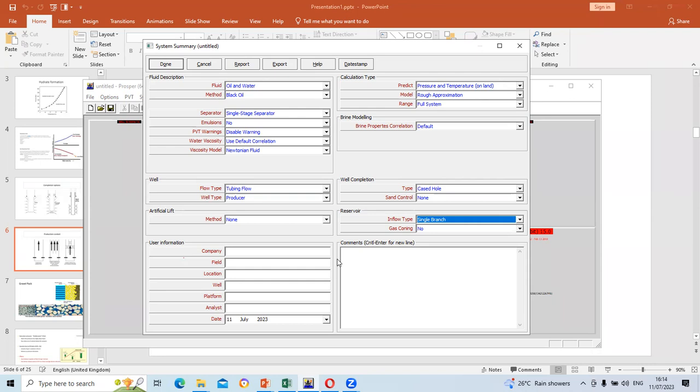The cementation job was not well done. So water is moving from an underground reservoir somewhere else and is now migrating gradually into the cement and then moves into the perforation. You may think it is water coning, meanwhile it is flow behind casing.